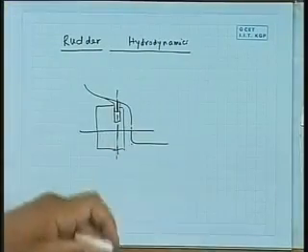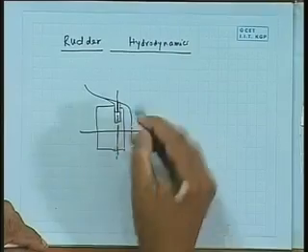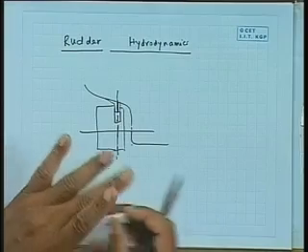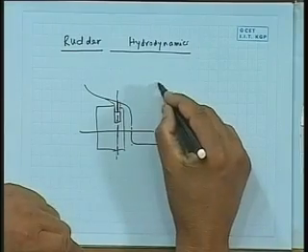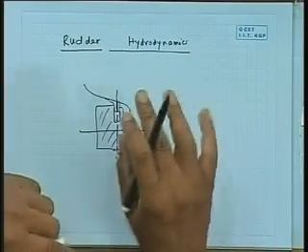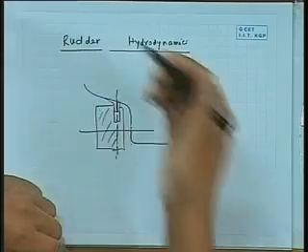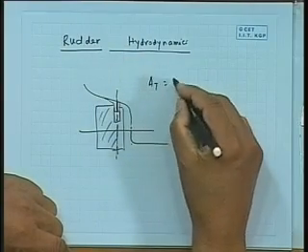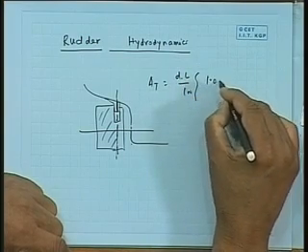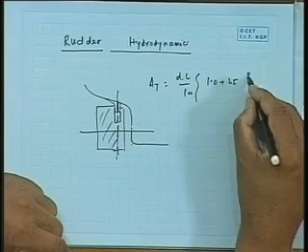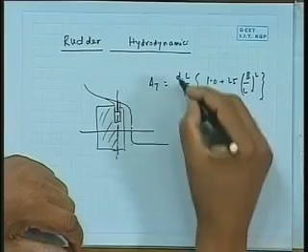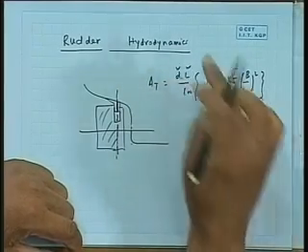So if you take a rudder here, something like that, it has got a rudder stock. It might have earlier had a rudder post, but as I said, I am not getting into the detail of the construction part of rudder. In fact, there used to be an empirical formula about the rudder area also, how much it should be. It turns out approximately 2% of the central plane area, or some other formulas are there, empirical type formulas, d into L by 100, something like that. I will just give you one formula here, etc., etc. And these various kinds of formulas. Obviously d L by 100 gives you the percentage.